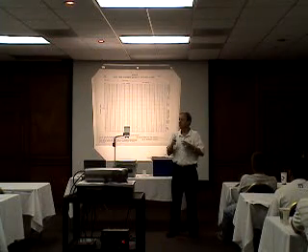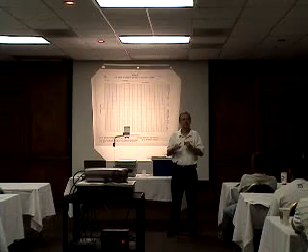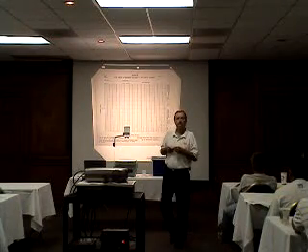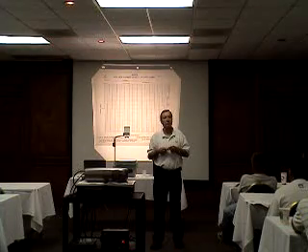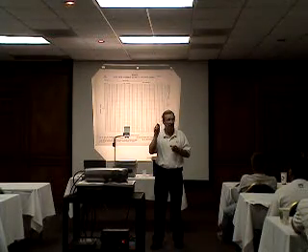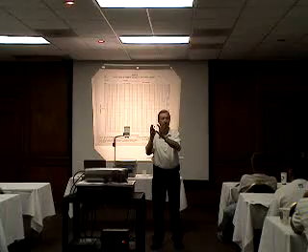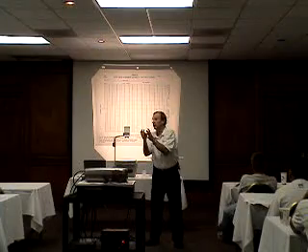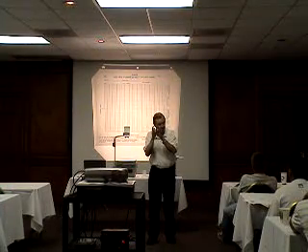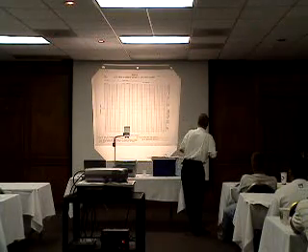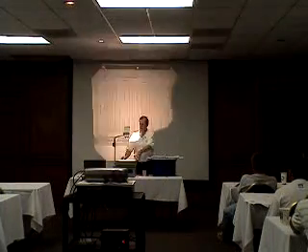What's the purpose there in just using those last 4 or last few numbers? To see if each test still is going to be within range of passing. Well, not only that, it's the samples you ran last month don't count what you did. Exactly. If I'm using that average to sort of try to watch what's happening, and I'm going to try to fix it before it happens, I don't care anything about what happened 6 months ago. That has no effect on what's going on here in these last few tests. So you just look at the last few tests. We pick 4 to look at, and that's sort of the concept there. Show you some of that